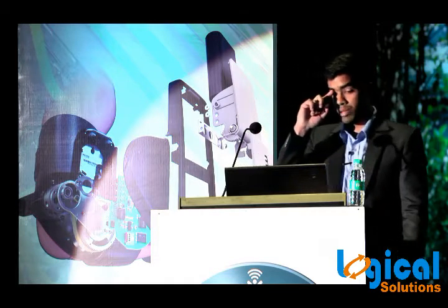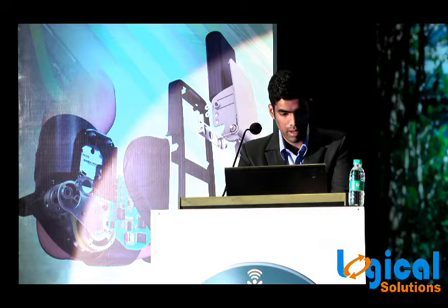Next we will see about the display states. If you click display state, this is already saved. In this display state, the whole part will be transparent and the holes will be clearly visible here. I am going to select one of them, and what I can do here is edit feature. If you have any favorite templates which you have added, they can be selected and browsed, and with a single click you can change the templates so that the size will be changed for all the holes.